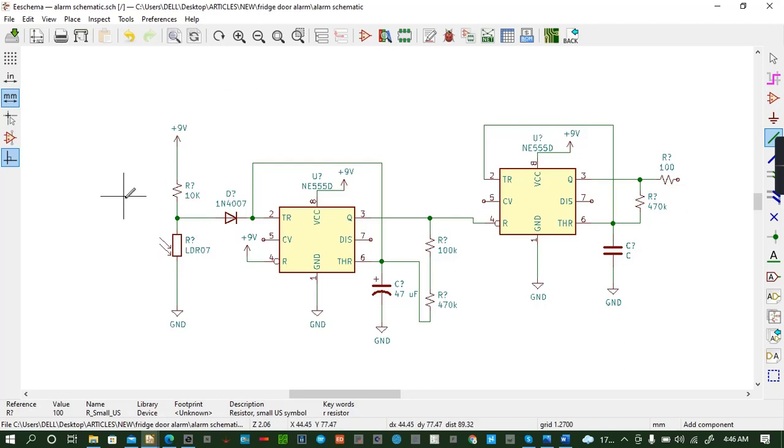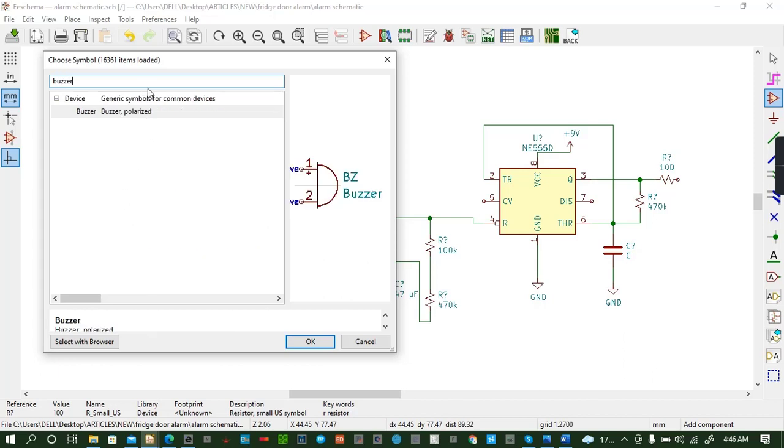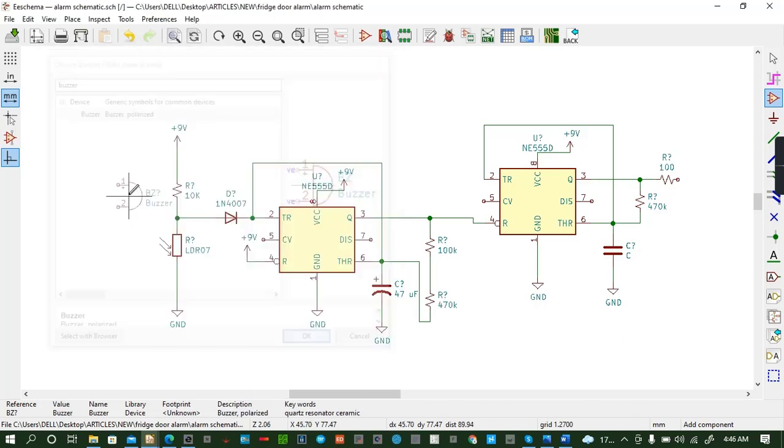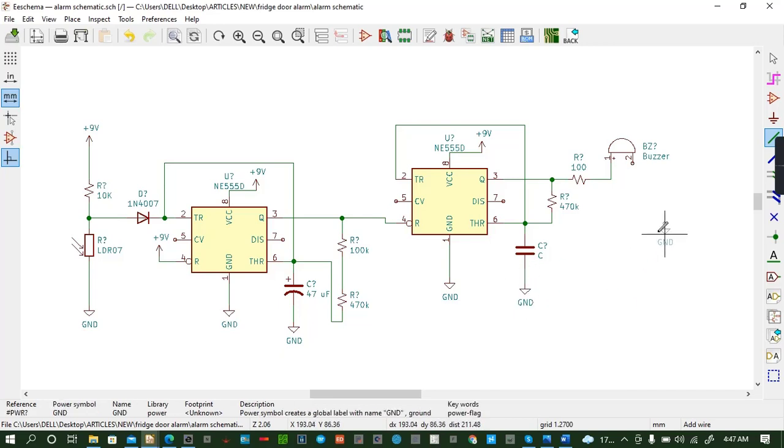Then from there you move to a buzzer. So you have to place a component, which is a buzzer, like that. You pick it, you come to this bit, you place it, press R to rotate it. You can rotate it the way you want, so you want it to look like that, and then we connect this wire to that bit. Control save. Then we ground, so you can copy this one. We ground this one like that. You can control save.